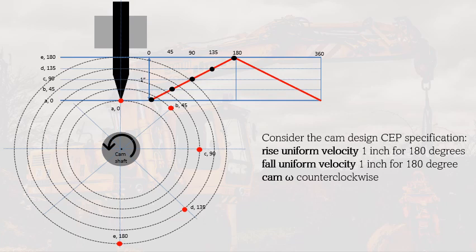As you can see, there is a symmetry between the first part of this displacement diagram and the second part. That means that in our cam profile, we will just have a mirror or a symmetry. That's the reason why we did not draw this part any longer, because we will just use the pitch curve that we can generate from the trace points.